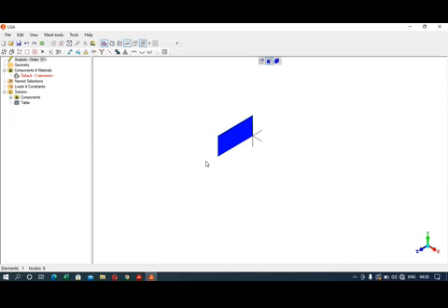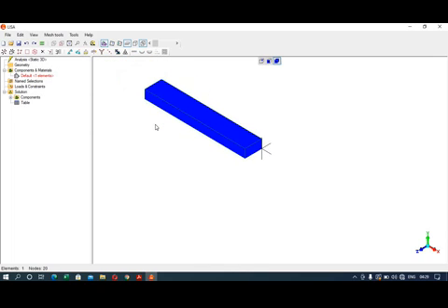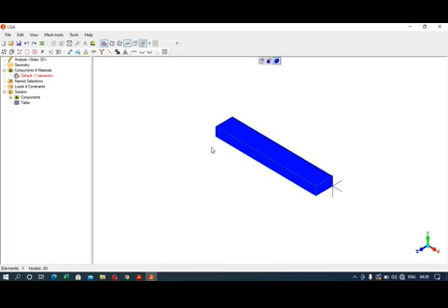and click on. So in the earlier example, the total length of the bar was given as 10 inches. So I will divide this 10 inches into 3 inches, 3 inches and 4 inches to create a non-linear geometry. Okay. So I will click on extrude and I will enter here along minus x-axis 3 value and number of subdivisions 1 to create a solid element.